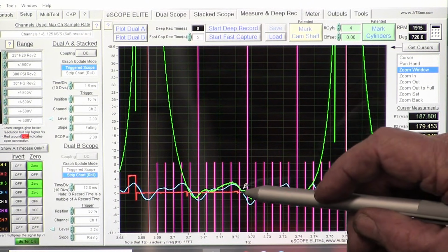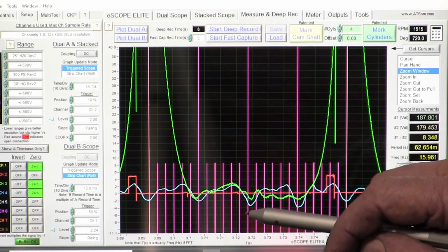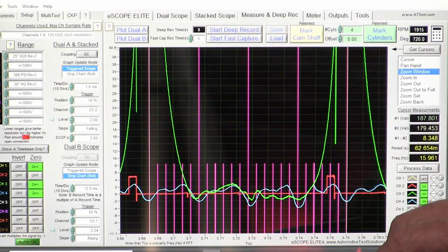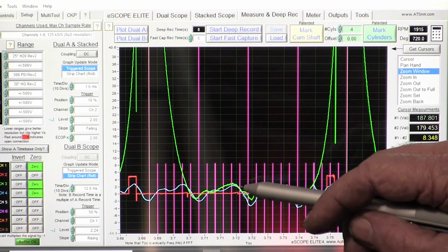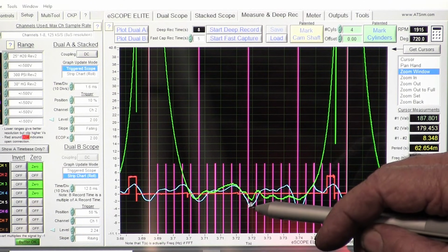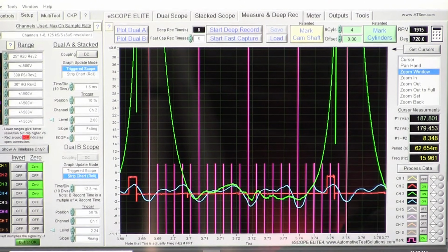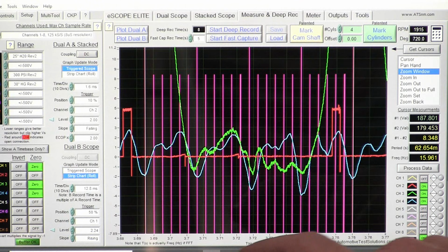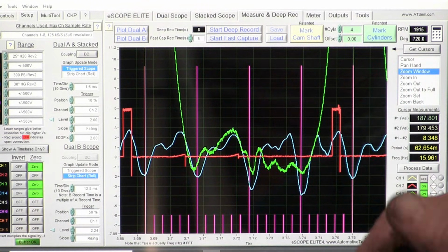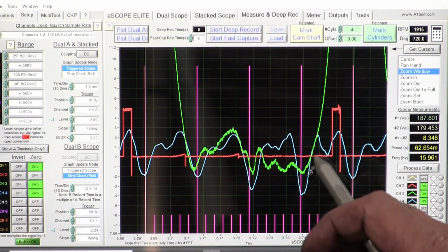Now, if that's 0, when that piston is still coming up, I'm pushing pressure back into the intake. So what that indicates is the intake valve is opening much too early, and the piston is still coming up on top dead center when that intake valve opened, and I'm pushing the volume of the cylinder back into the intake manifold. That's why every one of these is going positive. That again is indicative that the intake cam is out of time. So we want to go ahead, and I want to zoom in a little bit more on this so we get some more definition. We'll remark the cam. So right here we can see this clearly how far down this is going now. So we've got a problem.